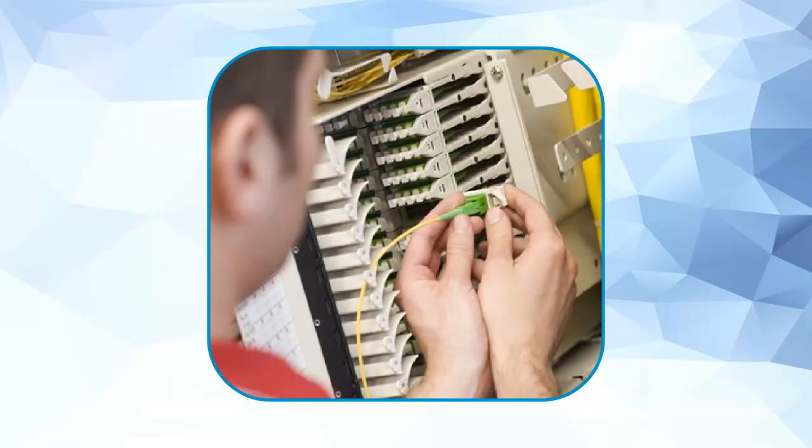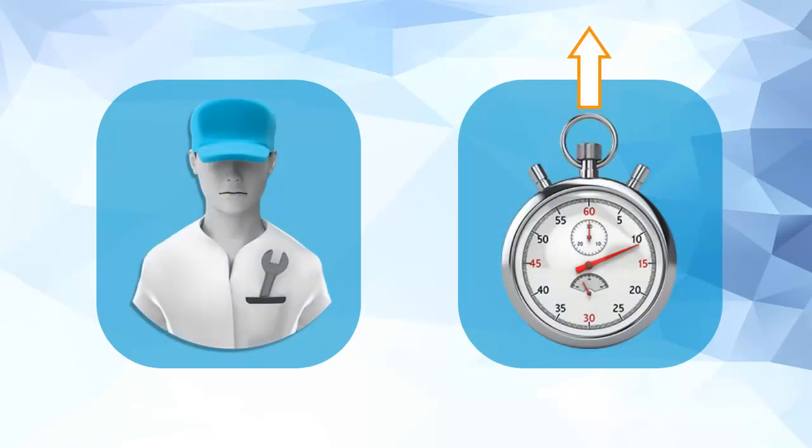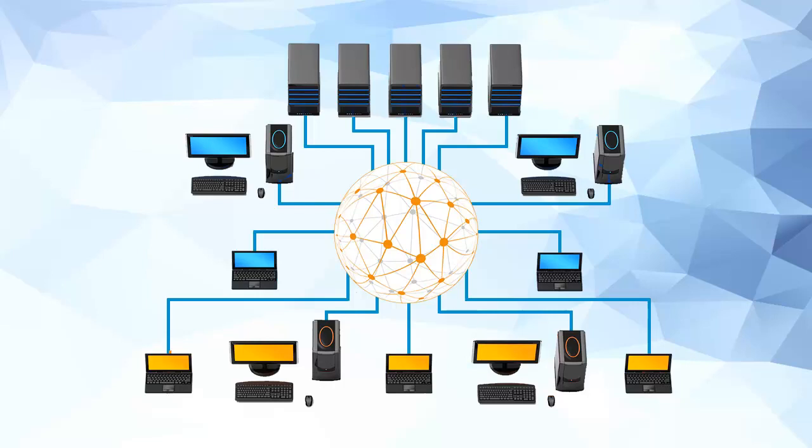In order to ensure that both connectors are properly cleaned, the termination panel must allow them both to be easily accessed. This easy access has to be for both the patch cord connector and the equipment or OSP connector on the backside of the termination panel. Accessing these connectors should not cause any significant loss in adjacent fibers. Without easy access to connectors, technicians will take more time to perform their work, delaying implementation of new services or redeployment of existing services. Dirty connectors can also jeopardize the long-term reliability of the network because dirt and debris can be embedded into the end face of the connector, causing permanent performance-affecting damage.